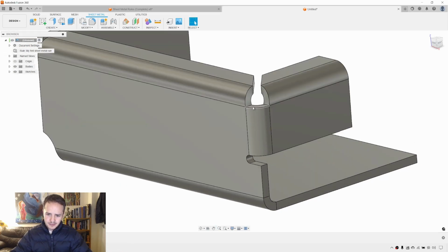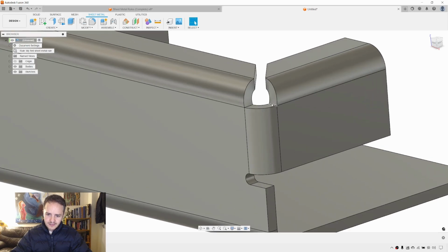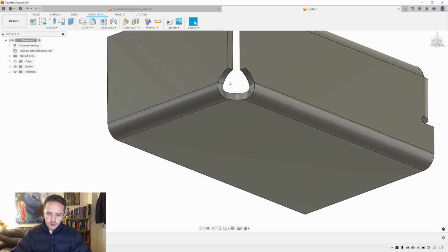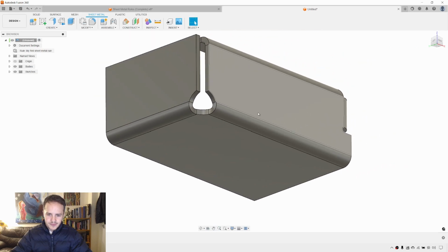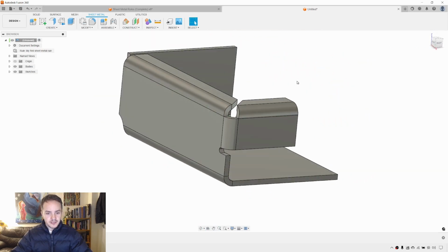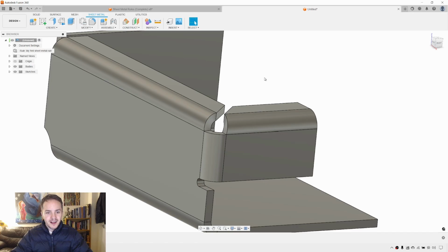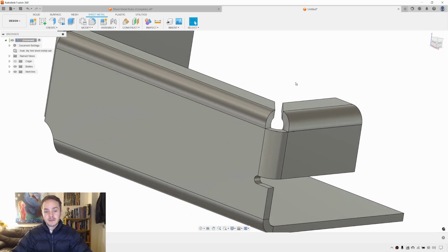So at the moment, we've got sharp little edges here. And in this corner, we've got nice and rounded all the way. If you are diehard and you don't want to wait for the bug fix to happen, we can edit it here manually, and I'll show you how. So it's a little bit of a workaround. If you want to skip this section because you're not interested, feel free to, but I'll show you how you can get a nice rounded intersection here at that 3 bend corner.